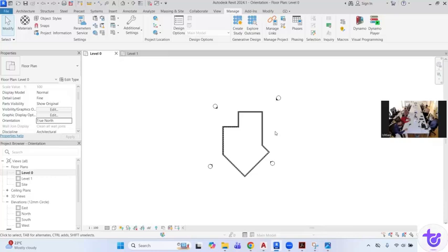It will come with the database which we have in Revit. When exported as an IFC, it will break level-wise, no? Actually, yes, it comes with many levels. But there are certain settings once you export the IFC, certain settings which we need to take care of, on how to export. And better you go ahead with the default settings to export the IFC without changing any setting, and then you can import it in the different versions of Revit.